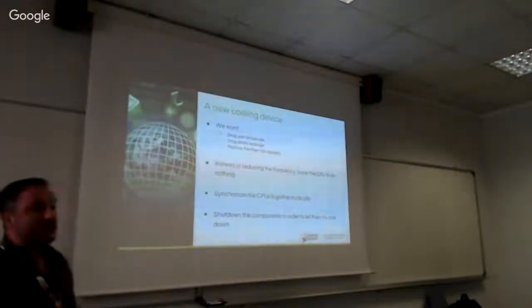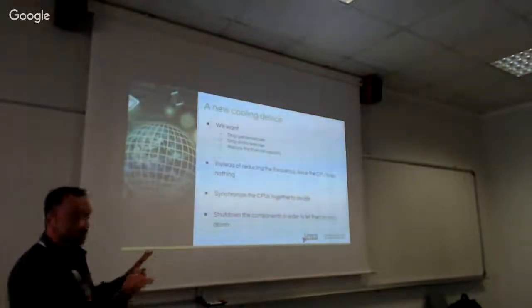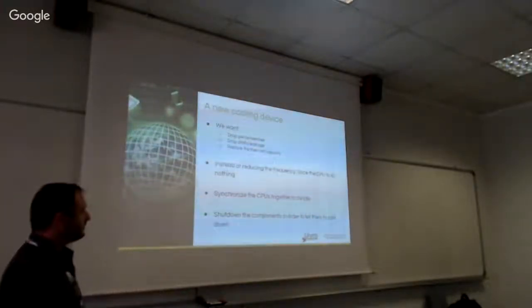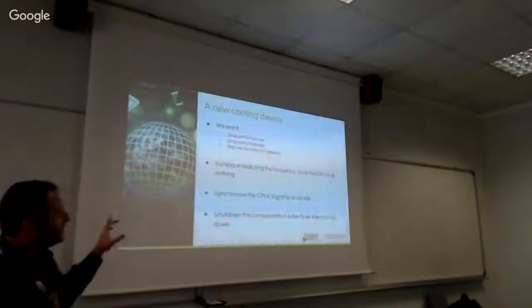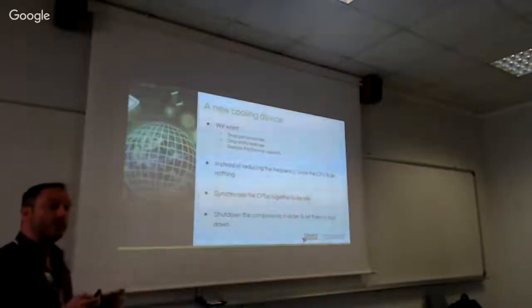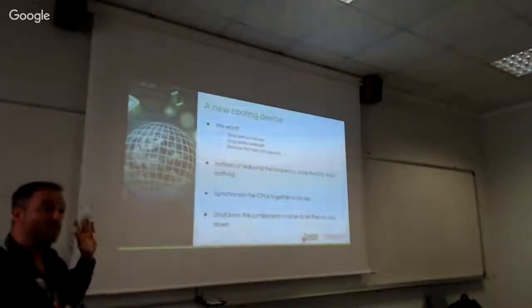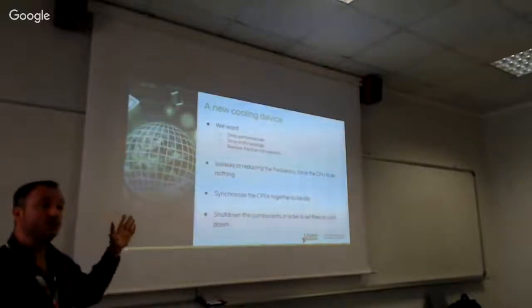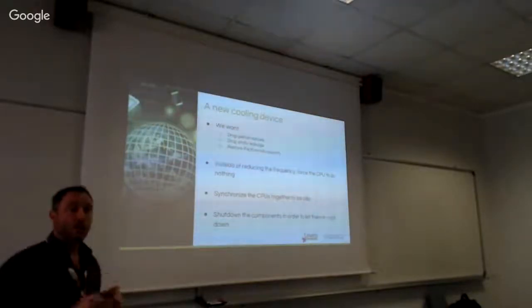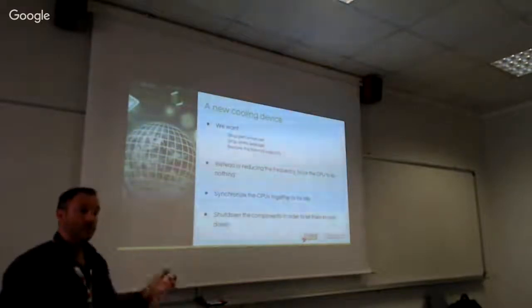There is a similar mechanism called intel_powerclamp doing that today, but it's a bit different. The idea is to synchronize the CPU idle at the same time, in order to give the opportunity for the CPU cluster to go down. Of course, all the cores belonging to the same cluster must go idle at the same time.